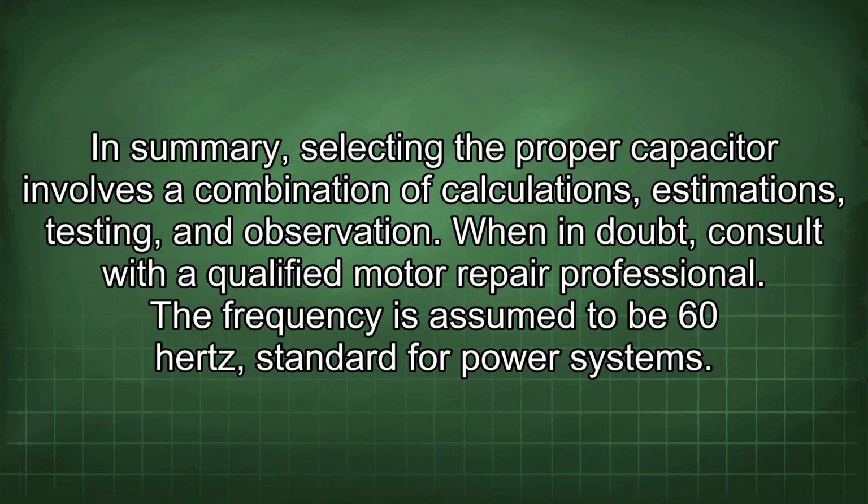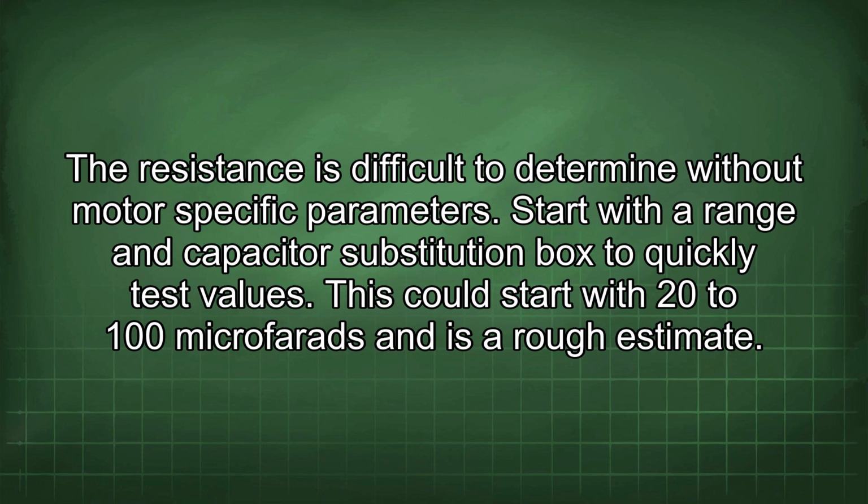The frequency is assumed to be 60 Hz, standard for power systems. The resistance is difficult to determine without motor-specific parameters. Start with a range and a capacitor substitution box to quickly test values. This could start with 20 to 100 microfarads and is a rough estimate.